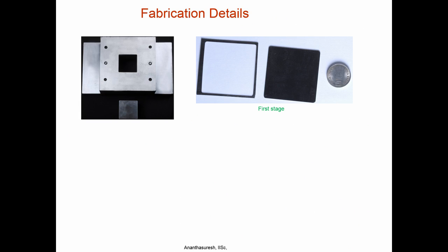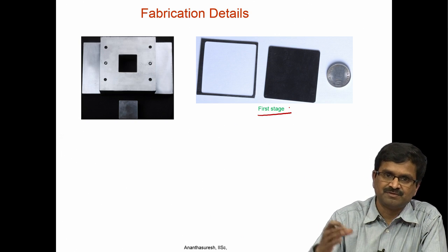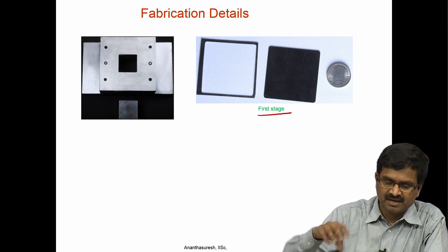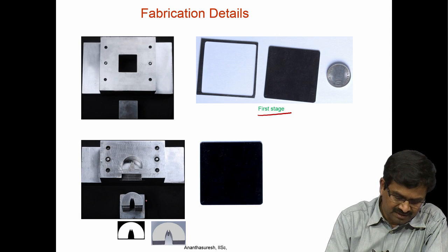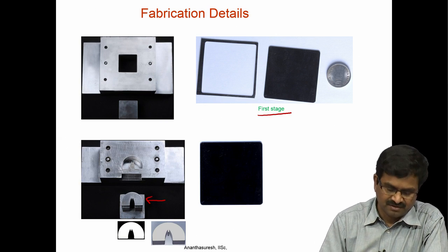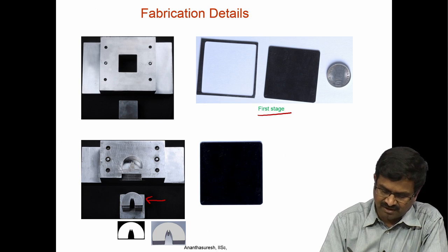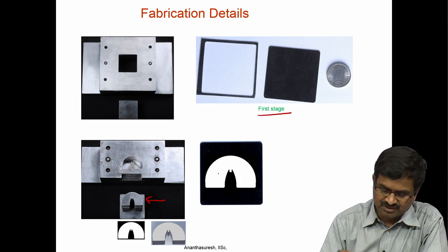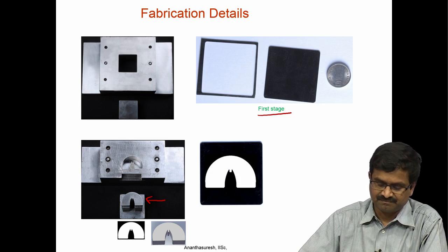First we take a sheet and blank it out. So, we get this first stage. Now we are making a square thing, and the die for that is shown there, and there is a matching punch for it. And then we make another die which is like that, which is going to punch this hole here. So, we get this thing out of this here. So, when you have that, we make this hole. Okay, that is one punching operation, and then take this to the next level.